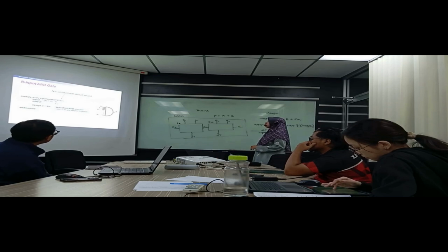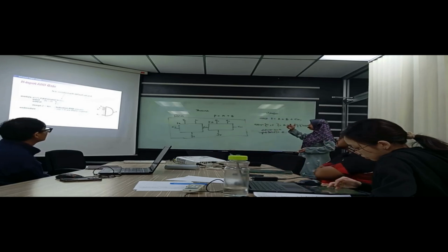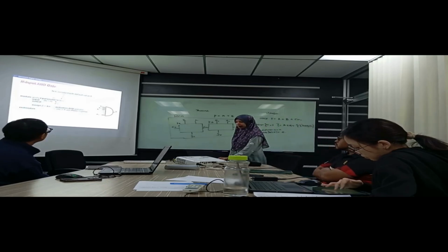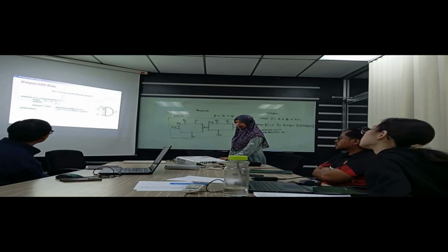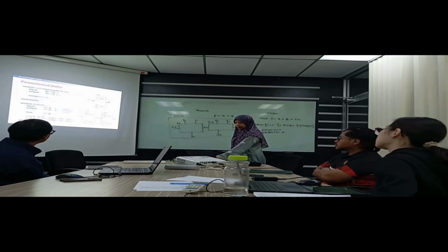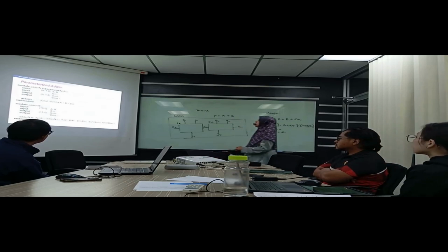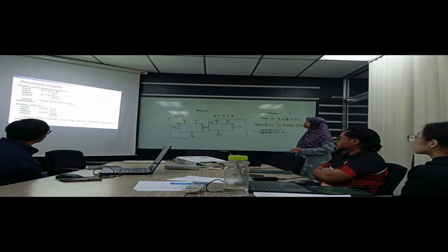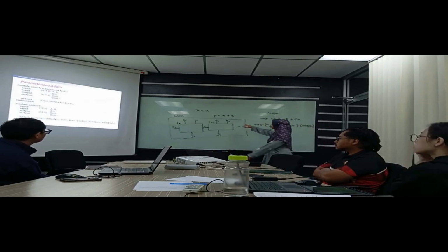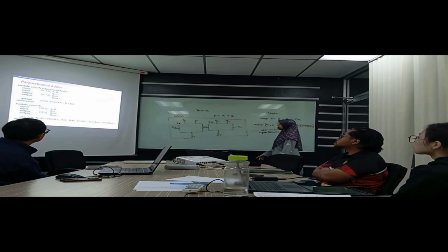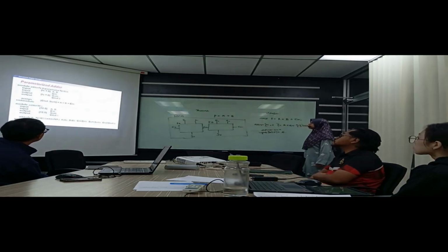Let's say you can change the size of the AND gate now. Any bit value, just change it at the end here, and the rest will follow. Also, if you use the parameterized adder, before I put A plus B as 4-bit, now I want to do it for 16-bit. So you can use it in this way.